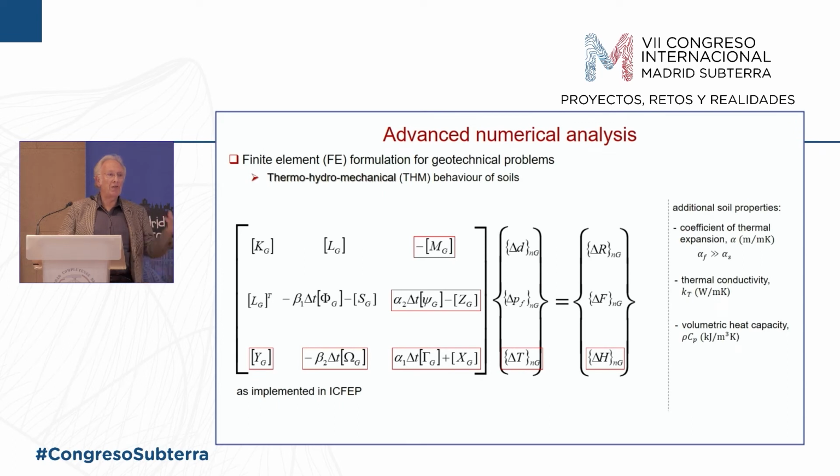So basically, if you heat something up, you'll get pore pressures in it, which reduces your effective stresses, which can actually cause the whole thing to fail, because its strength goes down. And of course, temperature affects both the density and the viscosity of water. So there's lots of cross-coupling in here. And we need these extra parameters to go in here, all of which are essentially non-linear.